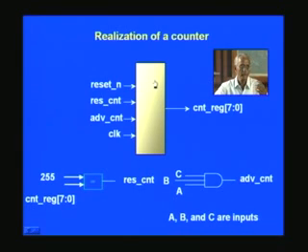Let us say 255. Then when the counter value is 255, there will be another comparison circuit here, and another signal will be produced here. We call it, let us say, reset counter, and apply it here in this block. And then once you reset the counter, you need to have another signal to start the count. So it's rather an enable of the count. That is what is implied here.